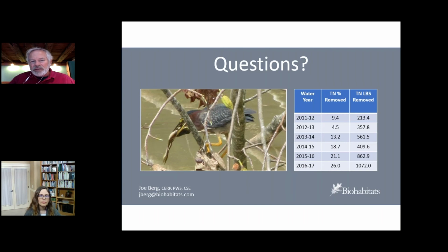Now they have membranes that they don't use gravel on anymore. So there's hundreds of thousands of yards of gravel in most cities that's sitting up on top of roofs that could be used in this way. So the beautiful thing about it is, because you're getting the biological process going in this material, which is going to help to maintain long-term porosity, we're comfortable with not having to use washed sand.